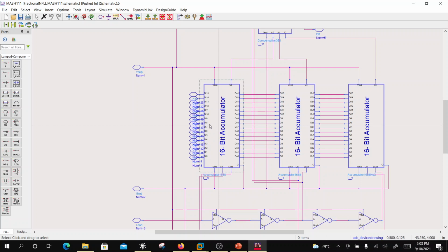Okay, the trade-off is either you have finer steps and better noise figure, or you have faster settling, right? So then you are settling in less than 2 raised to 16 cycles, but in this case you require 2 raised to 16 cycles for the right average to show up, right?